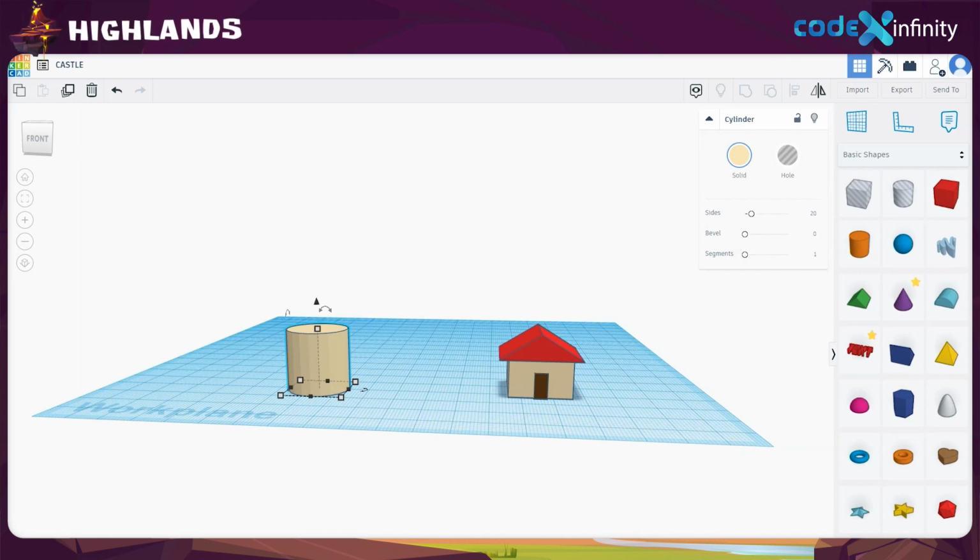And now what? Yes, the dimensions of the cylinder. To set the dimensions, click on the white handle at the right bottom of the cylinder and select the length value. Assign the length as 24 and press Enter key. We want the width of the cylinder to be also 24. So select the value of width and set it as 24. Then press Enter key. Now to adjust the height of the cylinder, click on the white handle at the top of the cylinder, then select the height and set it as 23. Then press the Enter key.